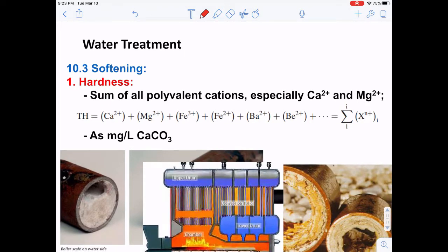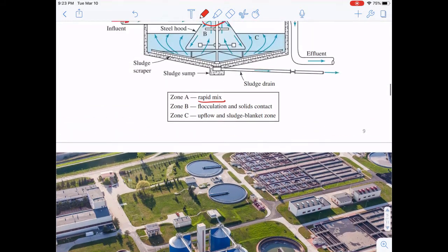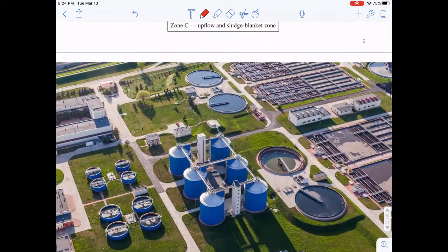So that is all about the coagulation, flocculation, and clarification. You can see that a serious process is needed, right? For coagulation, we need to introduce coagulants, and that is going to consume alkalinity, and further it will reduce the pH of the water.